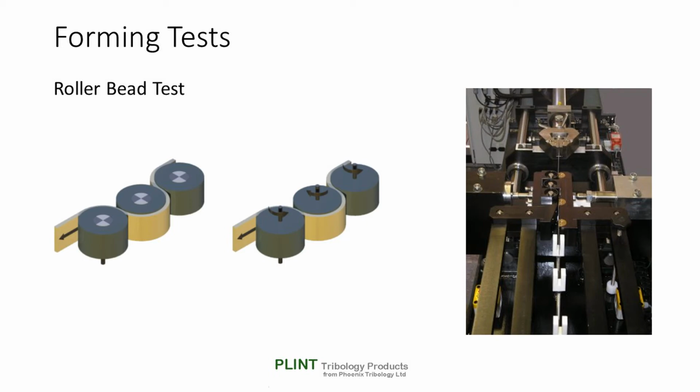The first action is to set the tool clearance, which may be done by using different diameter center rollers. A minimum clearance of 10% of the sample thickness is recommended, and the necessary center roller diameter must be calculated accordingly. In the event that the resulting drawing force exceeds the tensile strength of the test sample, the clearance must be increased by reducing the diameter of the center roller.